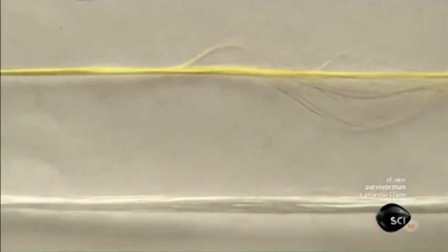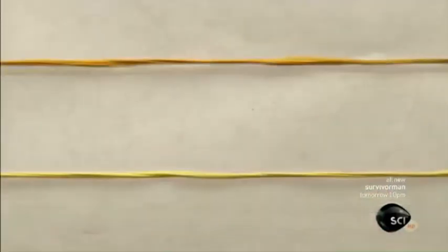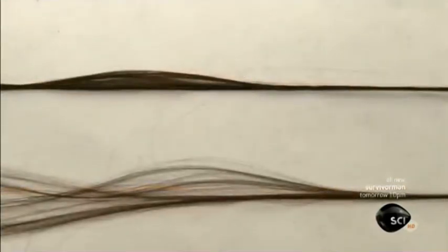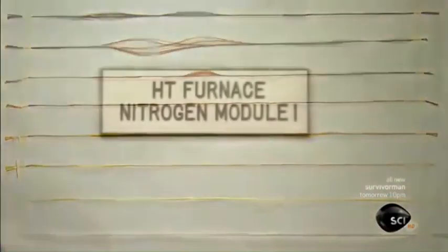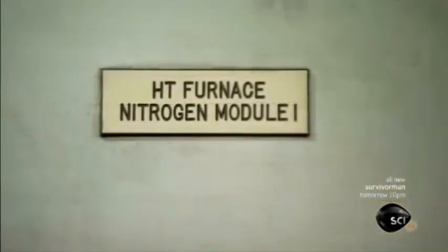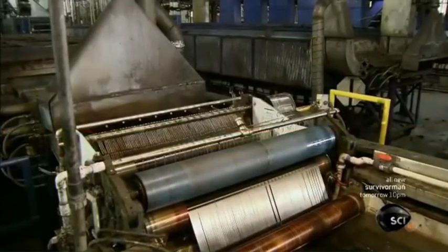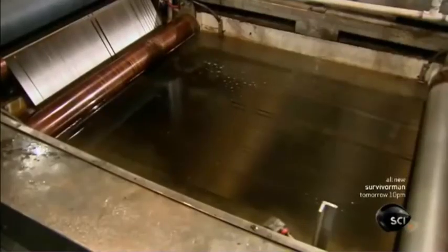As the fibers oxidize, they change color to eventually turn black. They're now primed for the next process, carbonization. Furnaces heat the fibers in an oxygen-free gas mixture. This expels the non-carbon atoms and transforms the remaining carbon atoms into tightly bonded crystals, running parallel to the length of the fiber. This gives the fiber its strength.